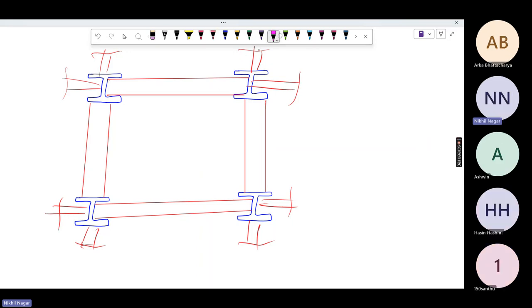Now, you already know your moment of inertia about this axis. I take this as YY and this as ZZ, and the X direction is our longitudinal direction. You will know that your IYY is higher than your IZZ. If lateral load like wind or seismic is applied to your structure, this orientation is perfect, because it gives more resistance with respect to the 90-degree orientation.